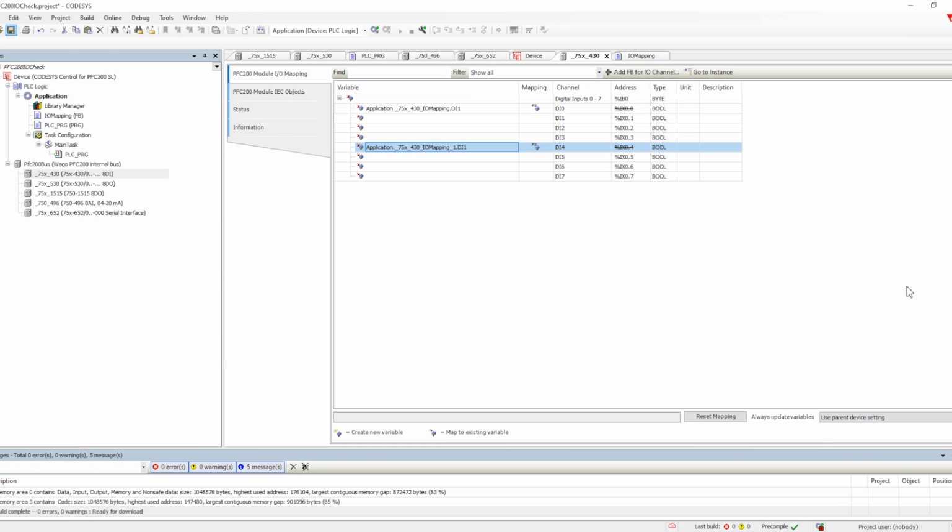Di1. Now if you see here, when I mapped it on the second channel, it created another instance. So the instance is changing for different channels. Another thing is that we can also define it, because we have defined two different variables in the VAR_INPUT, di1 and di2.